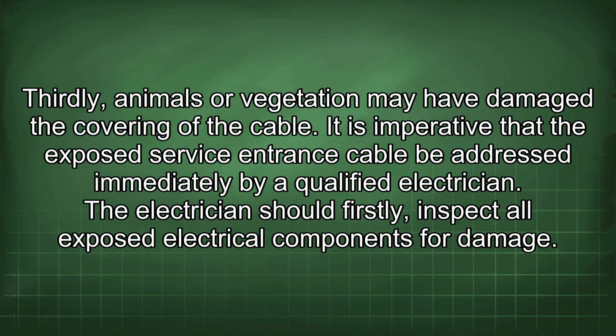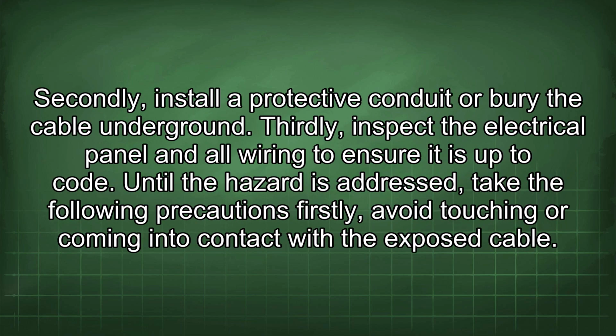The electrician should firstly inspect all exposed electrical components for damage. Secondly, install a protective conduit or bury the cable underground. Thirdly, inspect the electrical panel and all wiring to ensure it is up to code.